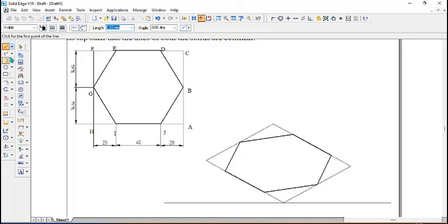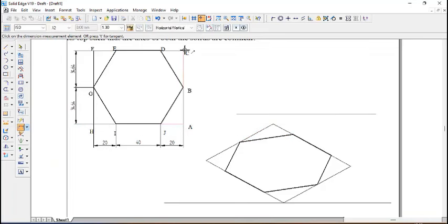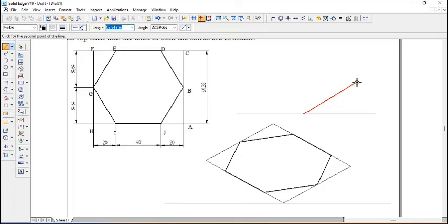Or else what you can do here is, there's one more way to construct this one. Once you take up the horizontal line, if you start from here, say any point, you can just draw one line from here to here. Because whatever the point G and B will come exactly at the midpoint. Okay, 34.64 and 34.64. So the distance between this line and this line will come 69.28. So we can just start like 69.28, enter 30. Okay, you will get this end.